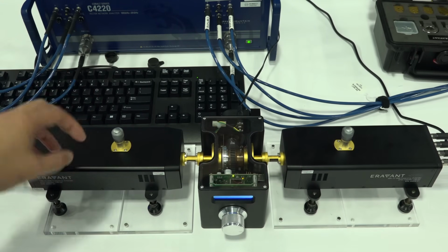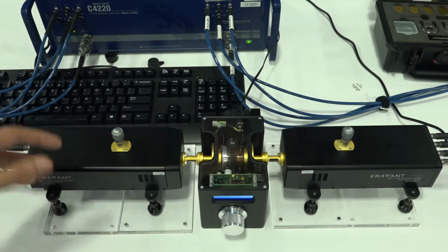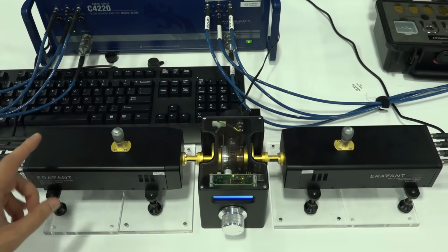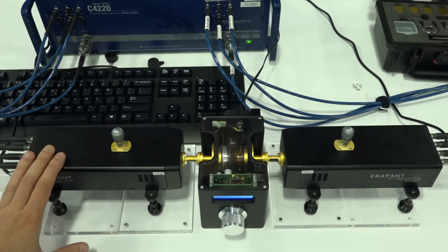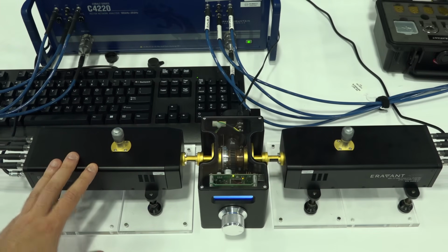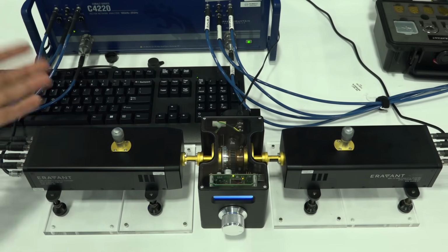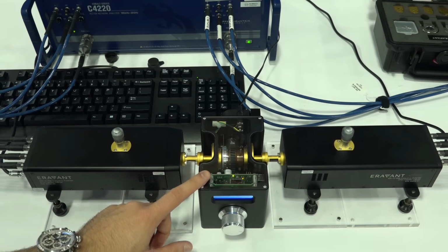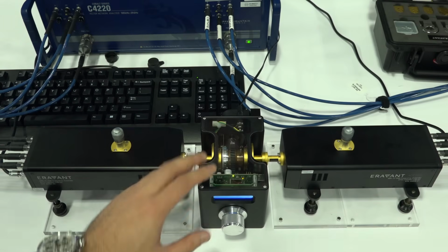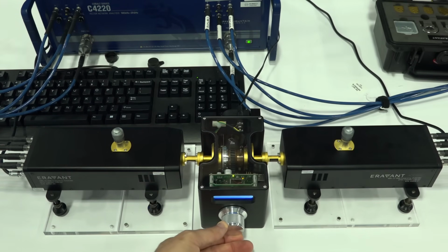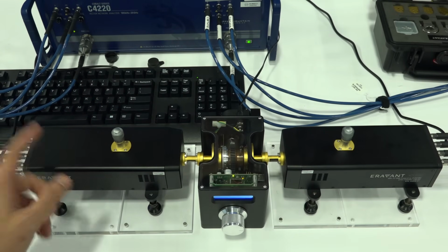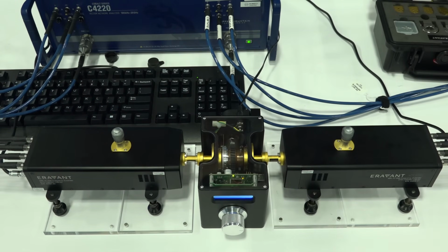Now, Eravant makes their own devices. They essentially engineer this thing from end to end, allowing them to lower the cost quite a bit. So apparently a pair of these is $30,000, which is a lot less than what's on the market. The output power is about 7 dBm, compatible with a variety of waveguide and coaxial interfaces for network analyzers. We have one of their electromechanical style attenuators where you can rotate things from the inside. You can actually see what's going on in here. So yeah, this low-cost version of these E-band with the extended frequency range definitely makes them a good competitive solution.